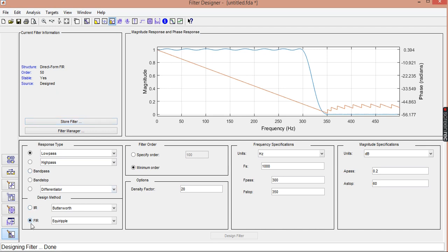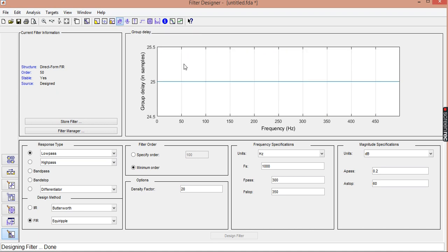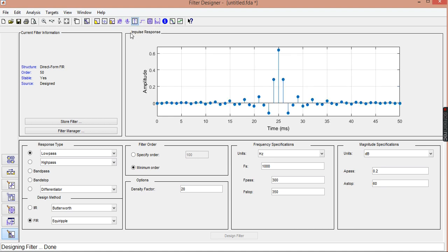Another advantage of designing a digital filter which is a finite impulse response (FIR) is that you have a linear phase response. Linear phase response means the group delay is constant. So this is your group delay. Group delay is the gradient, d phi by d omega. If you click on this, of course you are going to get a constant response with frequency, which means that if the frequencies start together, they arrive together; otherwise there's a phase distortion. So in music signal processing, for example, if you have an MP3 file or a WAV file and you're going to reject some frequencies, you're going to use Matlab to filter out that WAV file or music file or speech signal, whatever it is. If you don't have a linear phase, there's a phase distortion, and that's not desirable.